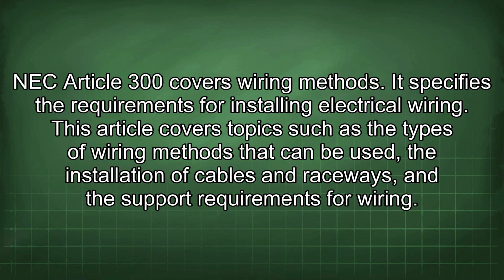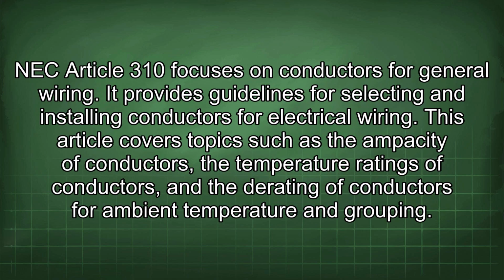NEC Article 300 covers wiring methods. It specifies the requirements for installing electrical wiring. This article covers topics such as the types of wiring methods that can be used, the installation of cables and raceways, and the support requirements for wiring. NEC Article 310 focuses on conductors for general wiring. It provides guidelines for selecting and installing conductors for electrical wiring. This article covers topics such as the ampacity of conductors, the temperature ratings of conductors, and the derating of conductors for ambient temperature and grouping.